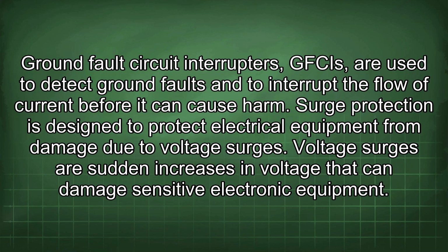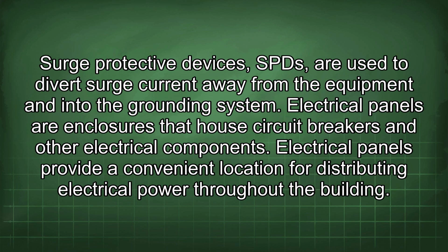Surge protection is designed to protect electrical equipment from damage due to voltage surges. Voltage surges are sudden increases in voltage that can damage sensitive electronic equipment. Surge protective devices, SPDs, are used to divert surge current away from the equipment and into the grounding system.